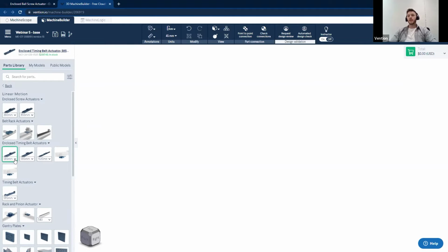Looking at it, the largest length of our piece's footprint is 1200 millimeters. In the drop-down menu, you notice that we have a 585 millimeter length, 855, 1530, 2295, and finally a 3300. In this case, the 1530 can possibly function, but if you take into account that the structure and the end of arm tool will make you lose a little bit of travel, it's better to opt for something a little longer or do the full calculations to validate. In our case, since I know we will need the slightly longer one, I'll opt for the 2295 millimeter actuator.